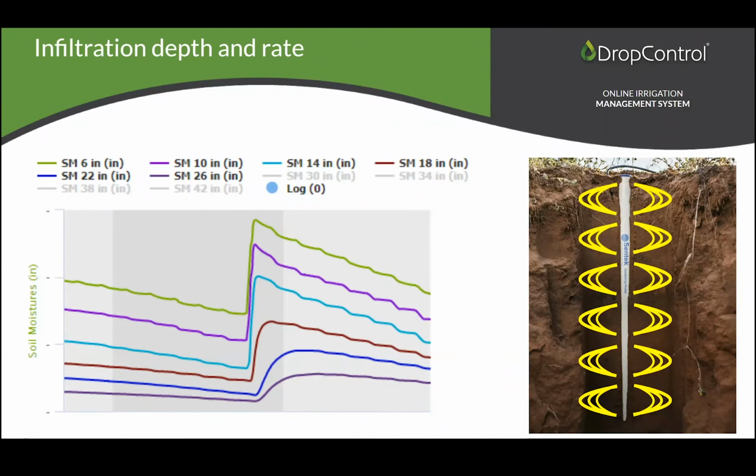And as I was saying, I've seen a probe installed with the slurry before. Again, the soil will adapt and compact back together, but that takes a few weeks or even months. So in the first few irrigation events, you've got to be super careful to understand that you're not looking at that preferential flow in the slurry. And the way to confirm that is basically going out there in the field and watching it.